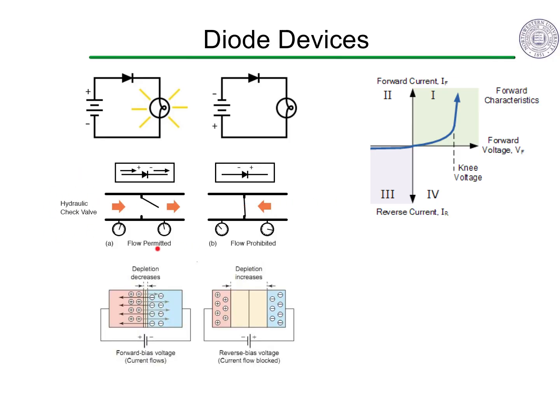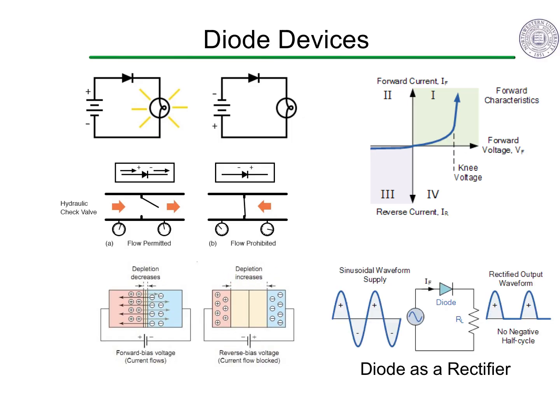This is because under forward bias, the electrons and holes are pushed together, reducing the depletion region and the barrier for charge to flow. While in reverse bias, the charges are pulled apart, with the depletion region even increased from an equilibrium value. If the bias is an alternating plus and minus AC signal, the diode lets only one direction of current through, effectively outputting 0 when the bias is in the other direction. This results in a rectification of the AC voltage such that only positive voltage is output, which can then be used to power a DC circuit.